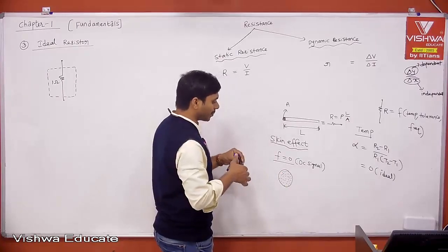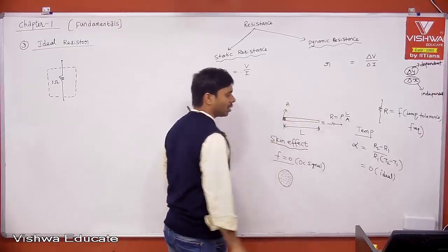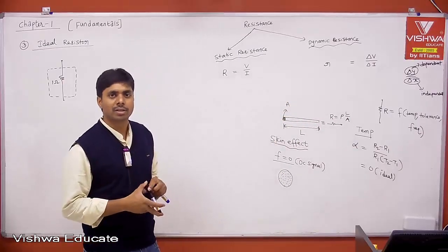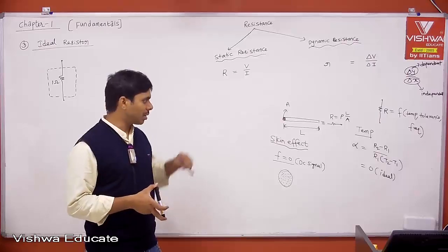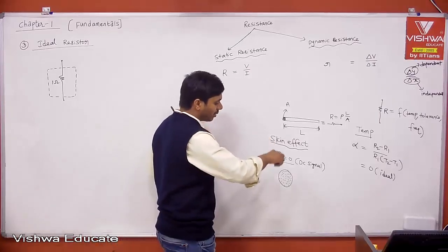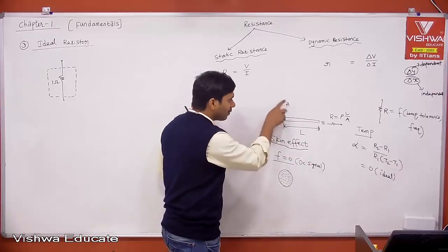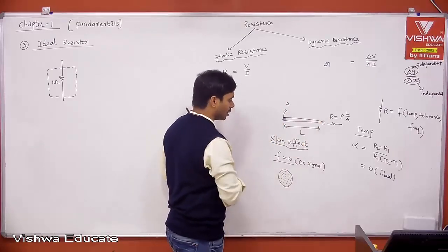Then all your carriers or electrons are moving from one point to another point. That is through the drift velocity component, because of the voltage or the electric field you have inside the wire. Now, when the free carriers are moving with an area of cross section of A, this is what gives the resistance.